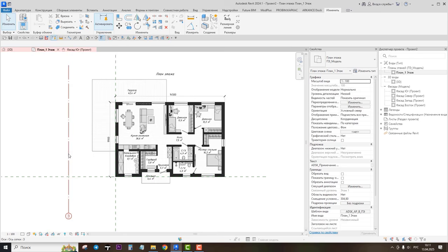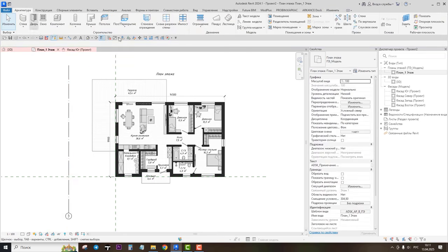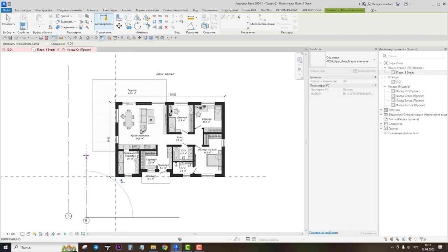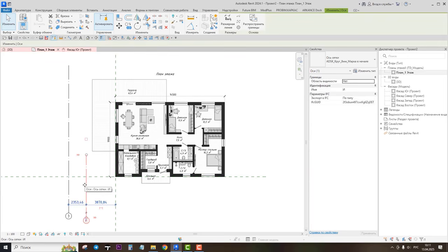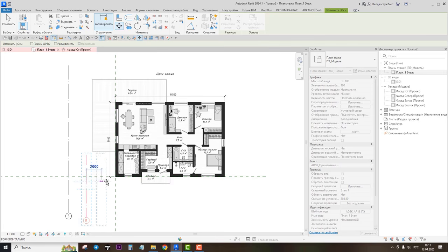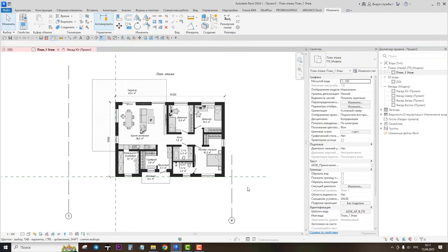How to control the tool, let me show you once again. Grid, left click, one more left click, and if I press escape 1 time, I quit this grid line, but I'm still in the tool grid. I can make more lines, okay? But if I press escape 2 times, I completely quit the tool. Remember. Let's select this new line, the tool move, and left click on this line and pull it here for now. Left click, double escape, okay?